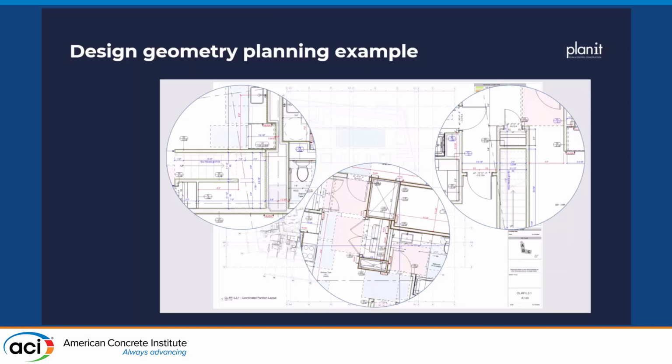So what you see here, I think I showed this on an earlier slide, is when we issue the revised drawings as an RFI, we color code the dimensions. Red dimensions are the dimensions that were missing from the design document set. Blue dimensions are the dimensions that we actually had to change due to conflicting information in the document set between disciplines, between sections and details and plan views, and large plan views and regular plan views. Then black is what we didn't have to change. We typically change between 60 and 90% of dimensions in a document set in order to make it work.